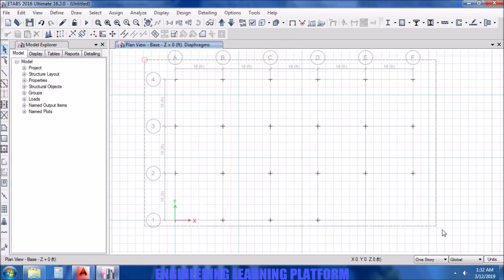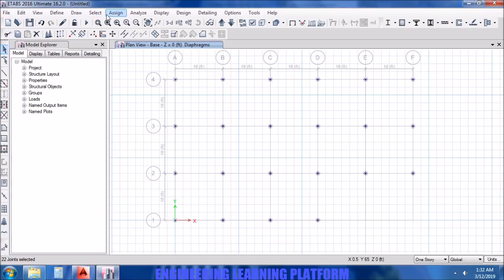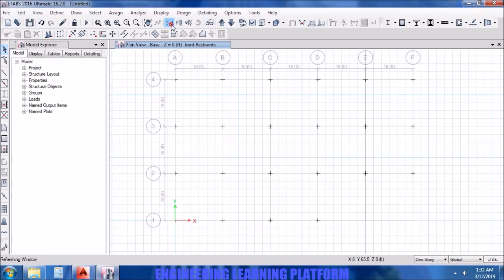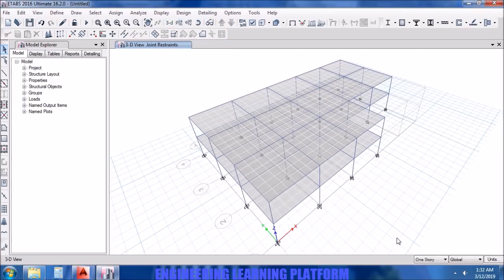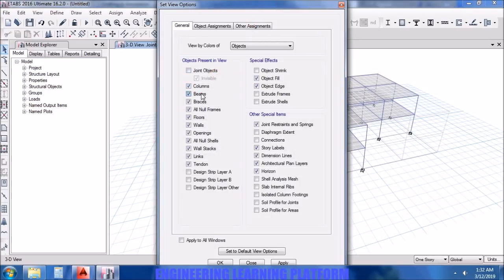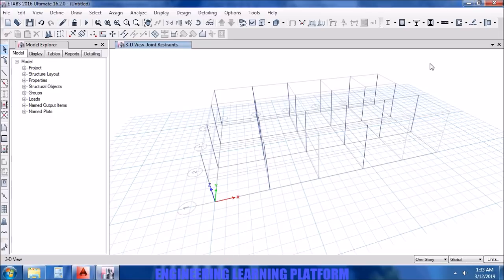Now the column supports are to be made as fixed. It's all on you whether you want to design the column's base as fixed or pin. If the column is resting on pile caps, then these supports are to be taken as pin, as pile caps or piles do not take moments or are not designed for taking moments. For now we are considering it's on isolated footing which takes moment. Also the raft takes moment.